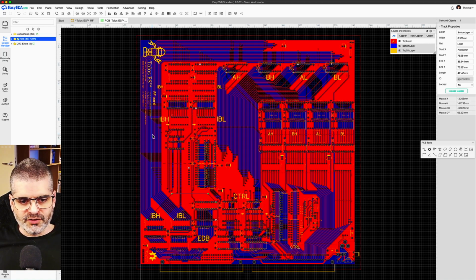For the bus, I could not avoid all the branching. As you see in this bus line highlighted in white, there are lots of branches. And it's unavoidable when you're designing a CPU. There are internal buses, you can't avoid it. You have to live with the reflections and take countermeasures like the 33 ohm resistors that I always use. But when I can avoid it, I do.